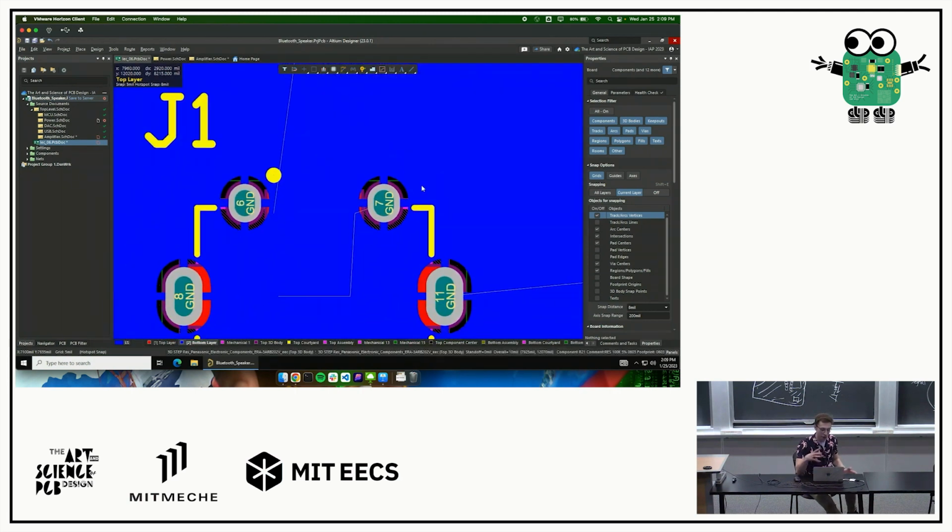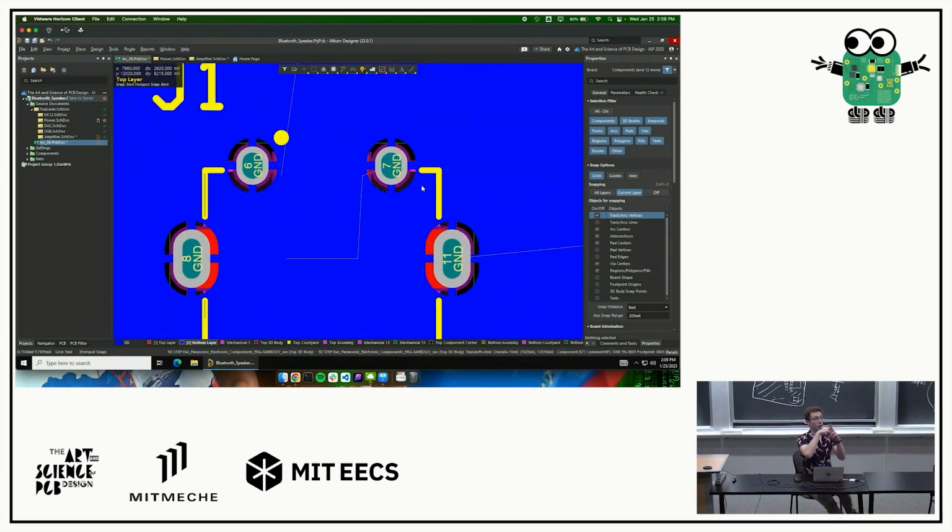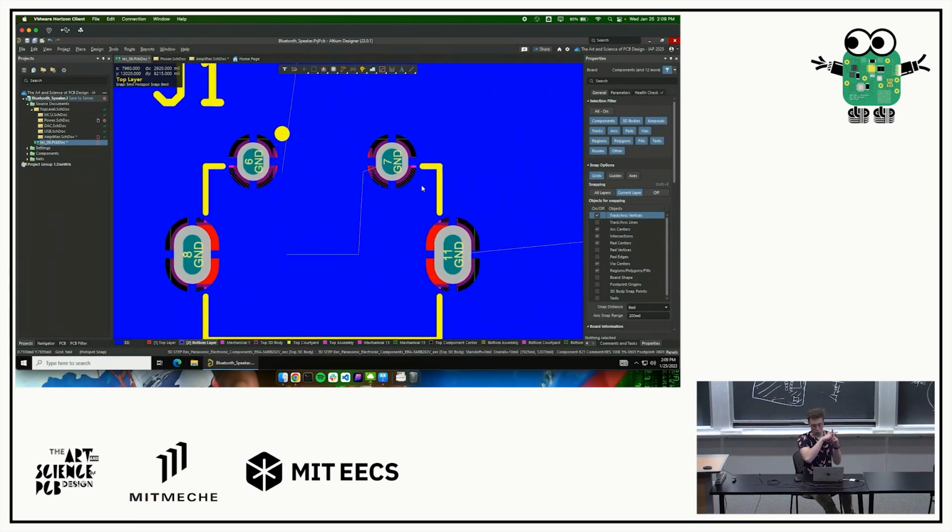You'll notice that those are connected to ground, and we now have these little star connections to those points. The reason why it's a star is because of some thermal stuff that's a little weird. But it's fine to leave that for now with the Altium default settings. It's connected all to ground for us. We now do not have to take a nice windy trace around the board in order to connect all the grounds together. The pour has done that for us.